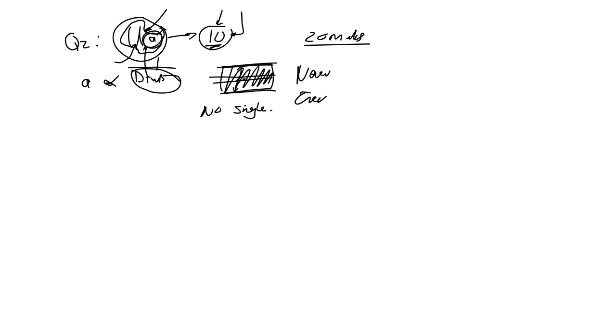What that reactor of Vogler hides from you is that it is in fact a packed bed reactor. That is a catalyzed reaction. He gives you the bed density, so you can calculate, and then he gives you just one big volume for his catalyst, or for his reactor. That big volume must consist of lots of tubes. And he doesn't tell you, so you've got no information to base this on, how many tubes do you have, Vogler? And what is the diameter of each of your tubes, Vogler?